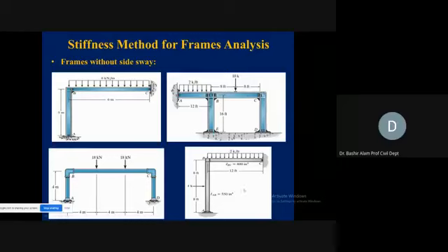Coming now to this last one, which is the bottom right corner. We have the horizontal load now for 4 kip. If you look at member AB, the vertical member at the center, we have a rightward directed 4 kip load. If I look at the load, and if I don't consider the support conditions, then the feeling is that it will have lateral displacement.